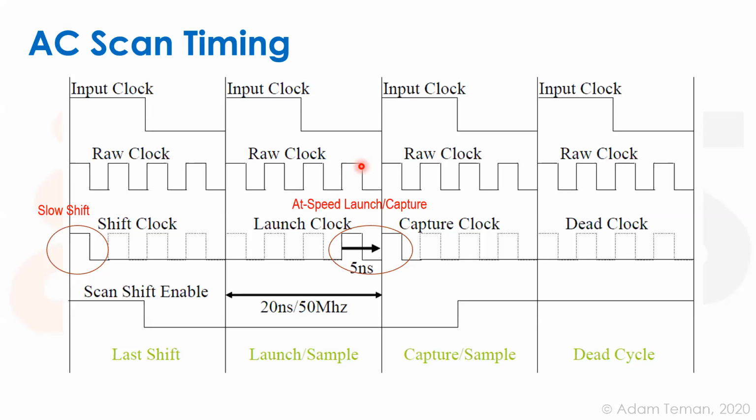So at-speed testing is done for sure, probably not by all companies. The coverage is questionable, and there's a lot of fighting about it in places like CDNLive or blogs. They complain a lot about at-speed testing. But I know it's a must to do, though it's not as robust as regular scan.